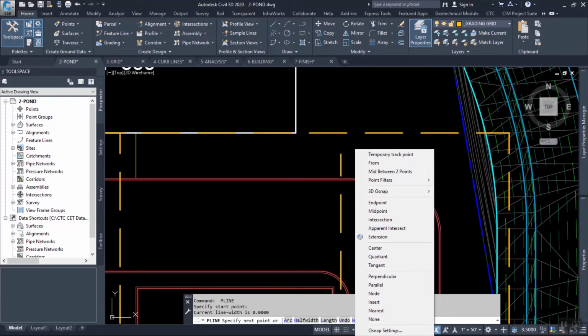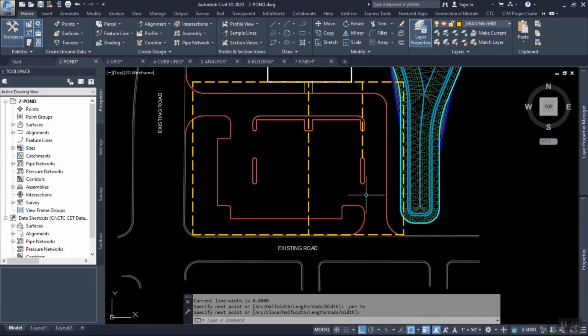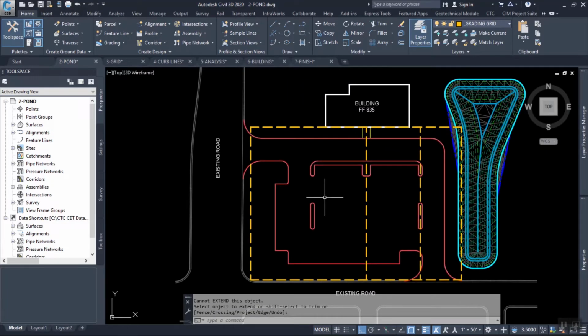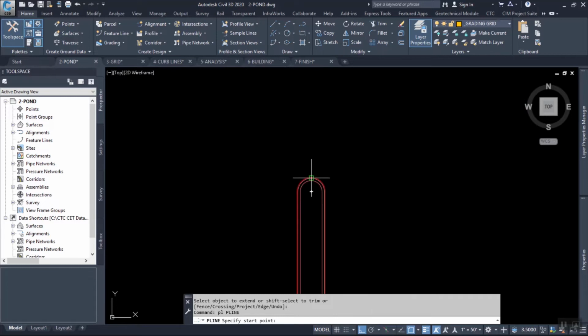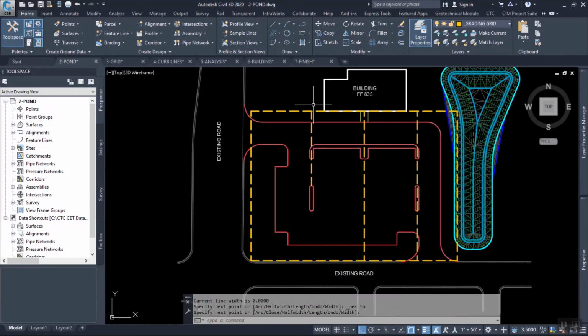And so you guys know this stuff when you're starting out on a site. You've done some analysis of the existing grade. Where does this need to drain to? Where is my pond, right? So where you put these starts to dictate, or rather is based on, what kind of drainage pattern you need across and away from your parking lot.